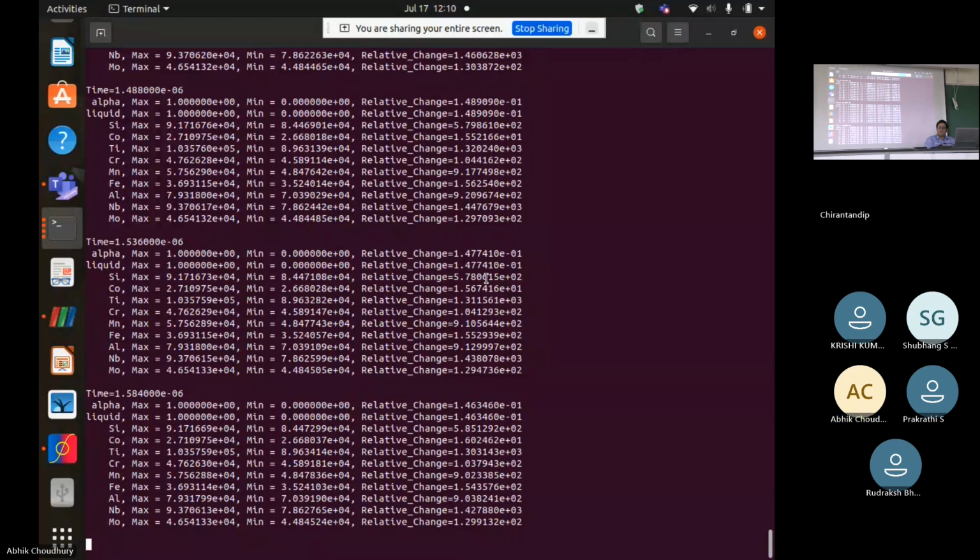Oh, hyphen. What is that? So Ni you add into the component list. It was missing, so that's what I showed them. You have to go to the phase component and add nickel at the end. And nickel will not appear in the solution because you only solve for 9 components. Of the 10, you only solve for the first 9, right? Independent.